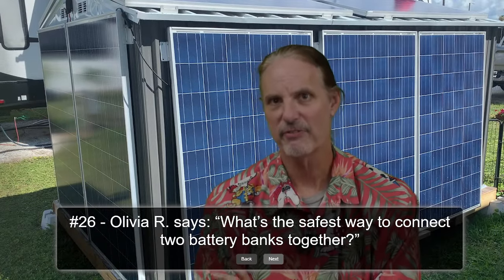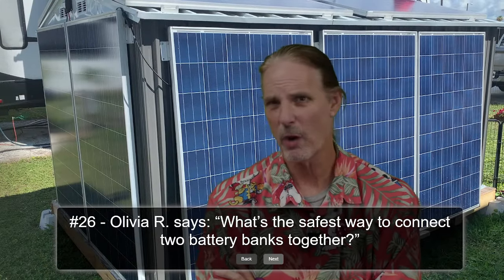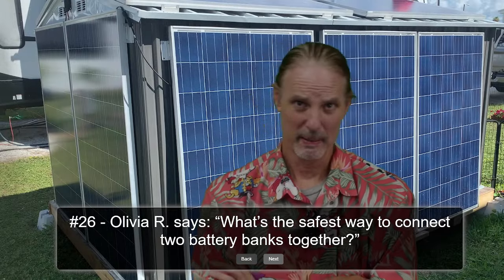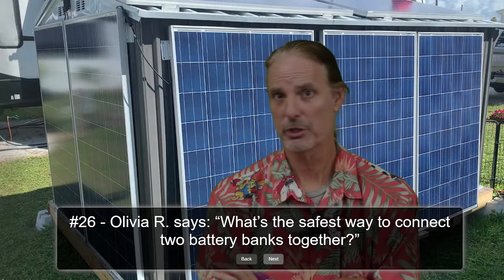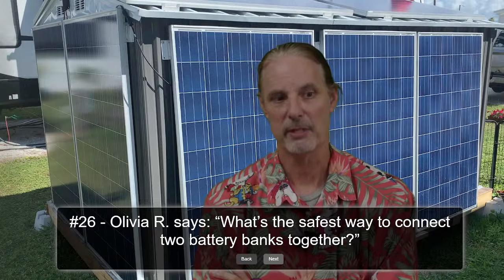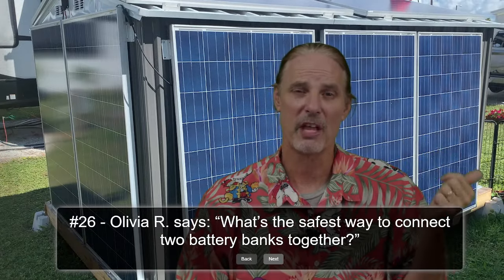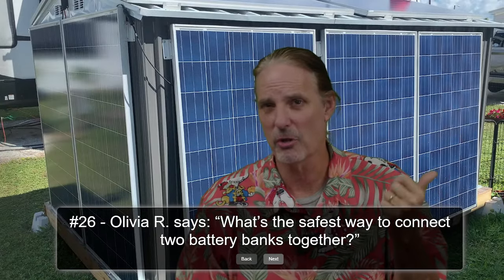They'll all be at the same capacity at that point, and then you can turn them all on at the same time. Don't do this while there's a large load. Allow it to be fairly idle at the time that you do it. Turn them on. Make sure that you don't see any big flows between batteries or big pulls, which, as long as they're all at the same voltage, or at least all fully charged, you won't see any, and that would be the safest way to do it. And that's the short answer. There is a much more elaborated answer at the beginning of the live stream, so if you missed that, I suggest you go back and look at it there.